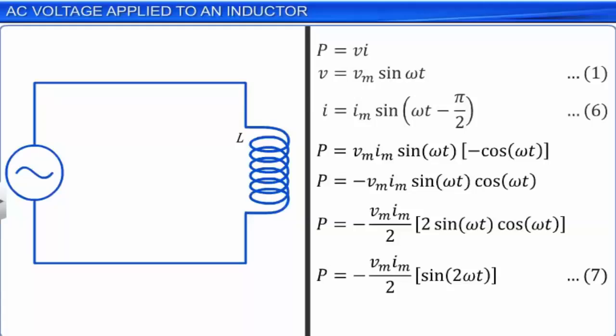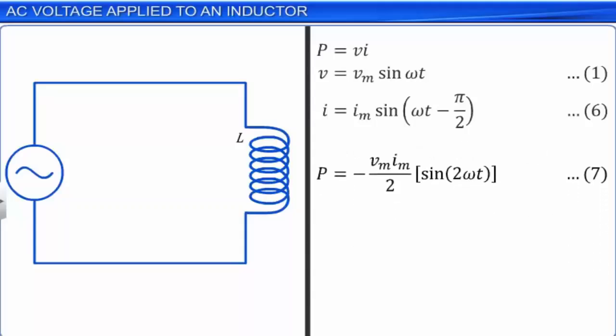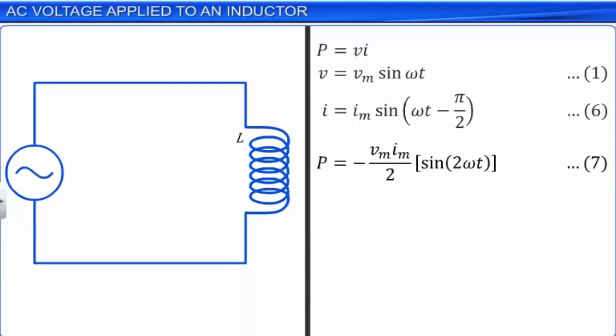This instantaneous power evaluates as a time-dependent harmonic function. As this is a time-dependent sinusoidal function, its average over one complete time period will be 0. The argument of the sine function for voltage is omega t, and for power is twice omega t. Hence, the time period for the power function is half the time period for voltage.